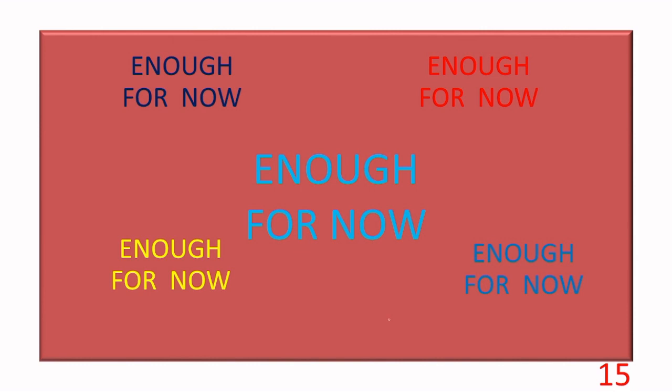To recap, in the present session we focused on the functioning of the device, how it is able to provide amplification to the signal given at its input terminals. During the functioning, there exists mutual interaction between the electron beam and the input signal. This interaction is described by two equations, the electronic equation and the circuit equation. These two equations are introduced. Some important points regarding the operating characteristics of the TWTs are also described in the present session.